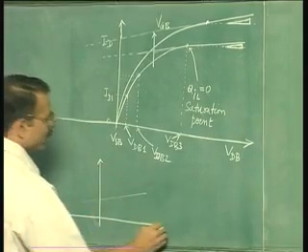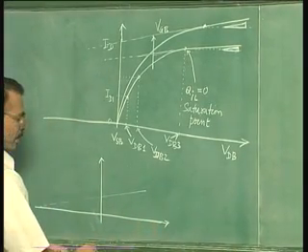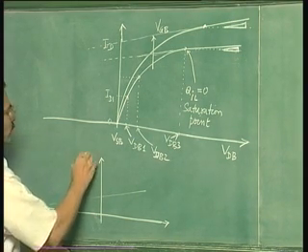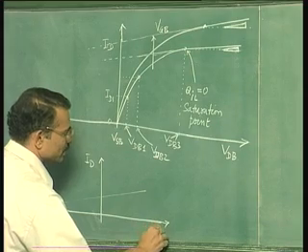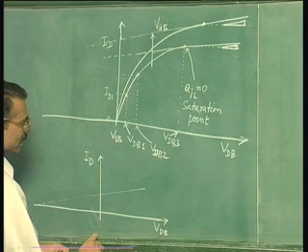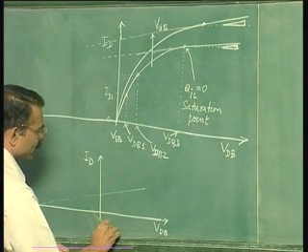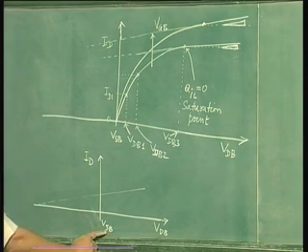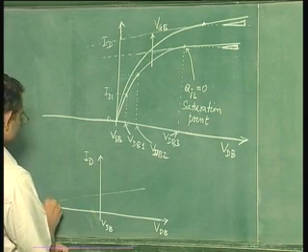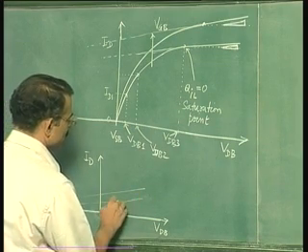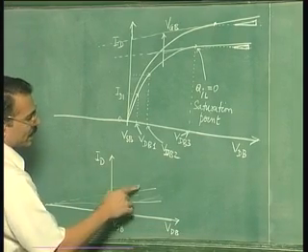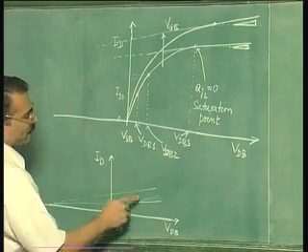So in fact, the way to draw the saturation and the ohmic region characteristics clearly is as follows. Qualitatively, if a student is asked to sketch the drain current versus drain voltage characteristics, this is VSB here, we are taking the bulk as the common terminal. The current voltage characteristics will look something like this. So we first draw a set of lines like this, all starting from one point, each of which represent the current in the saturation region for different gate bulk voltages.